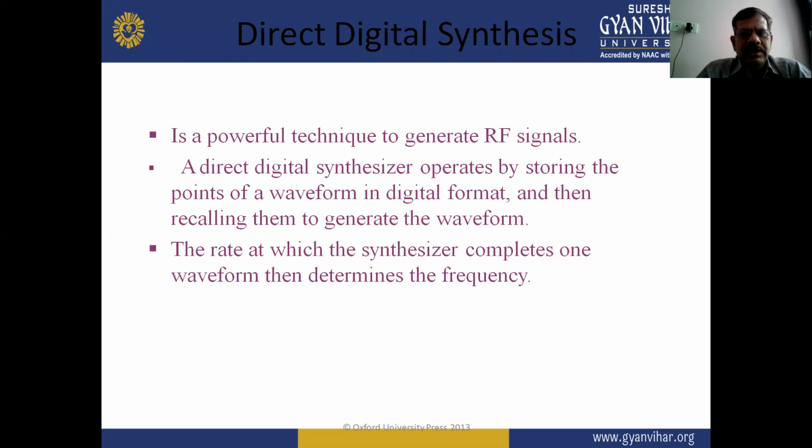Next one is direct digital synthesis. Direct digital synthesis is a powerful technique to generate RF signals. A direct digital synthesizer operates by storing the points of a waveform in digital format and then recalling them to generate the waveform.